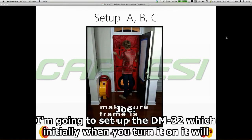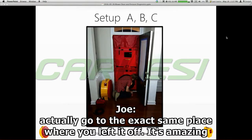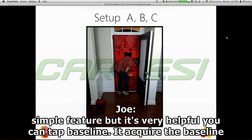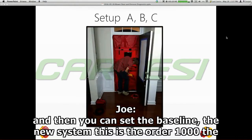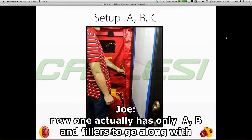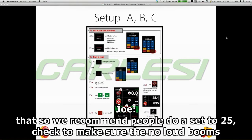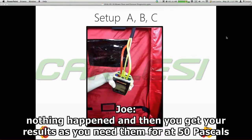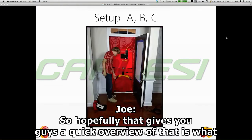And now I'm going to set up the DM32, which, when you turn it on, will go to the exact same place where you left off. It's an amazing, simple feature, but very helpful. You can tap baseline, it'll acquire the baseline, and then you can set the baseline. The new system, this is the older 1000, the new one only has an A, B, and fillers that go along with that. So we recommend people do a set to 25, check to make sure no loud booms, nothing happened, and then you get your results as you need them at 50 pascals.